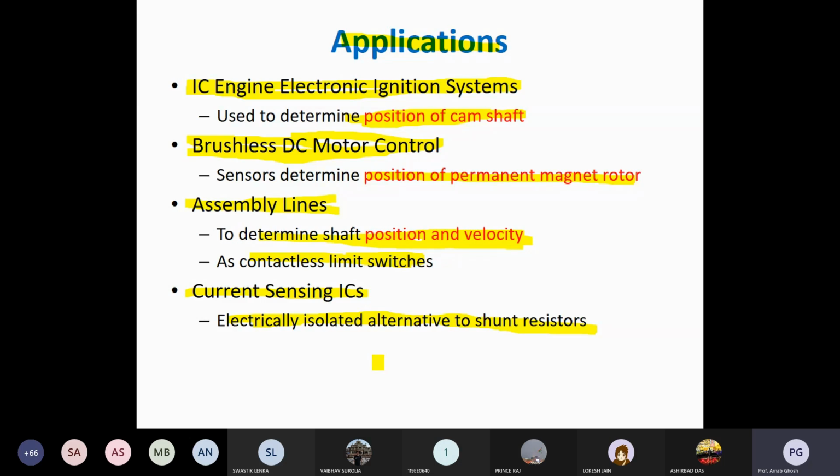That huge amount of voltage will be carried by the power electronics devices. But in the control circuit of those power electronic devices, the maximum voltage is more or less 15 to 25 volts. So if any kind of fault occurs in your power circuit and that fault comes directly to your control circuit, then there is a big problem of controller damage. That's why isolations are sometimes required.